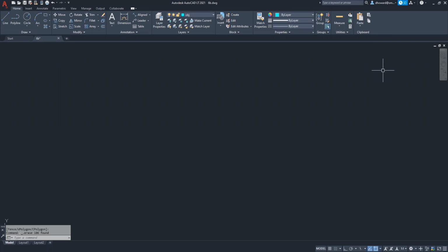So we are doing the primary view of the radial swing block. That's basically a side view where everything will be shown true size. So we are going to begin in our construction layer with the traditional construction line cross.